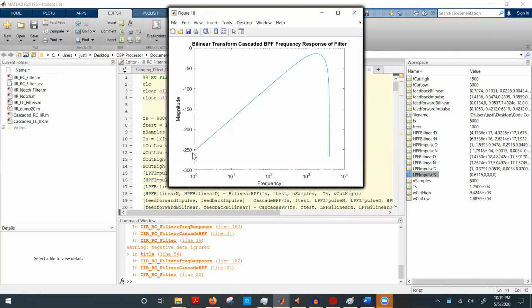You notice that this bandpass filter, the band doesn't actually ever reach completely 0 dB, and that's because when you have the high pass filter and the low pass filter, the total bandwidth is very narrow. In order to actually reach a gain of 0 dB, or 1, with the high pass filter, it requires being well within the pass band, but at the same time we also have to be well within the pass band of the low pass filter.